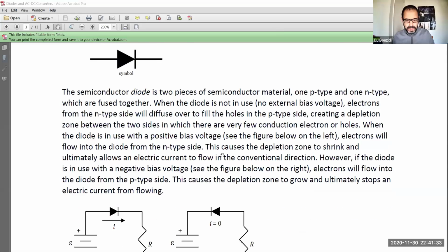You can clearly see the legs are different in here, okay? One of them is the anode and the other one is the cathode. And you have to be careful when you're connecting them. If you flip them, the current will not work. And this is one convention; there is another one for the long ones that I was telling you earlier. It's color coded, okay? Well, at least the strip next to it. So having that in mind,